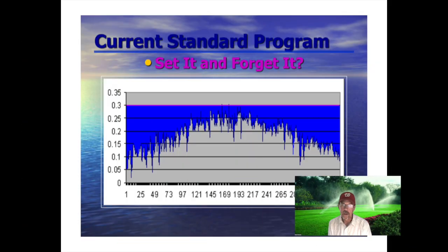After design and installation comes initial programming and setup. How the initial programs are developed and then adjusted going forward will have a huge impact on how your system operates. Here are a few things that often go wrong at this point. Controller is set in the spring to a midsummer schedule and not adjusted during the growing season. Here is a graph example demonstrating how much water is wasted in spring and fall.